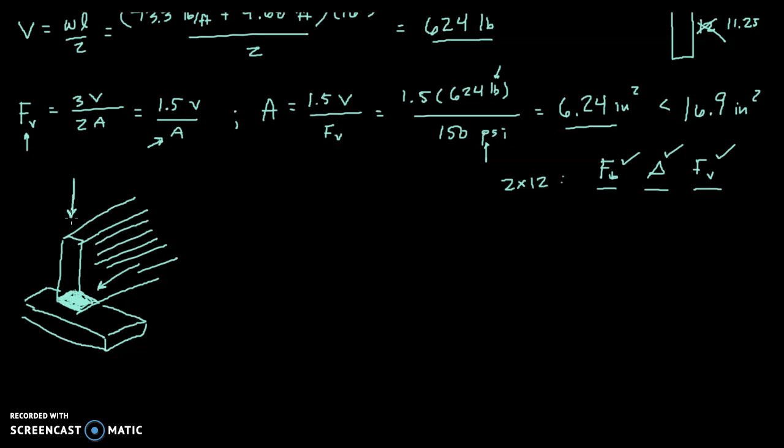And this bearing stress of all the weight that this beam's carrying resting on this little area is going to be perpendicular to the grain. So we have to make sure that this area is big enough so that the stress doesn't get too large. By increasing the area, we can spread out the weight and therefore decrease the stress.